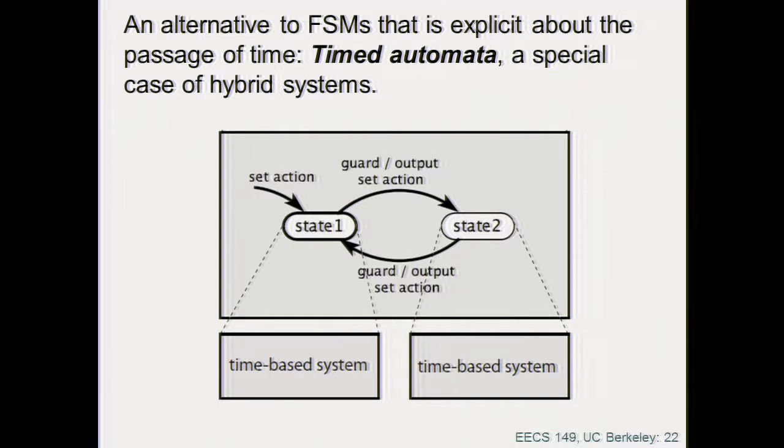So if by any chance the generator breaks, what happens? Boom, right? And it's not that you don't see your movies, right? You go down because you can't do anything to the plane. There is no mechanical system. It is all electric. So what do you have to think about? You have to give redundancy, right? So you've got to have at least two motors, right? Two generators in the plane. But now, so you have the right generator and the left generator. And you have buses that take the power to the appropriate part of your system.